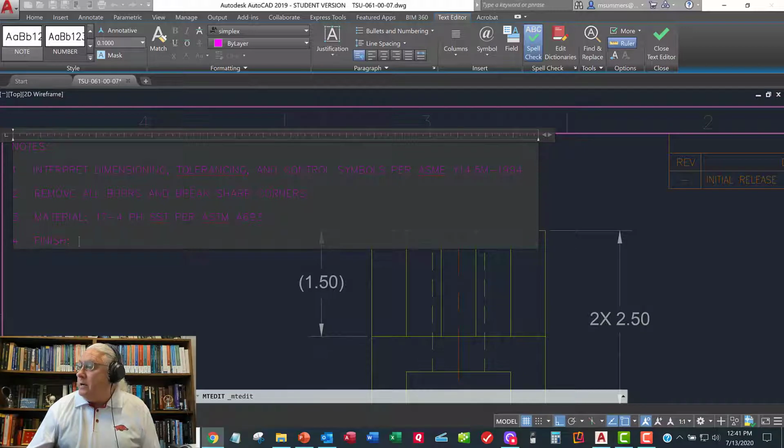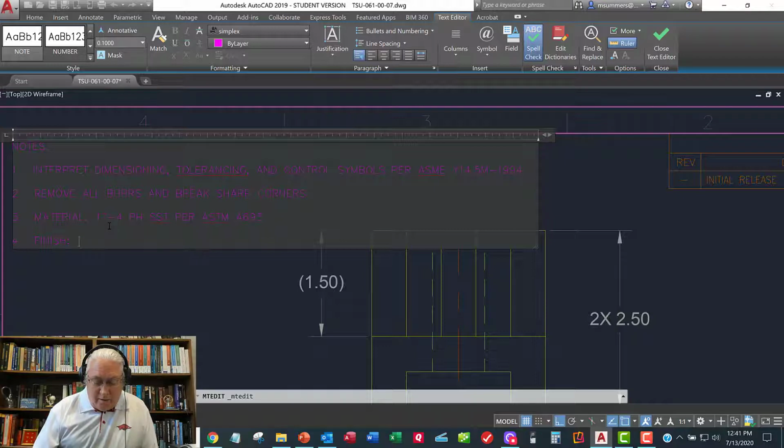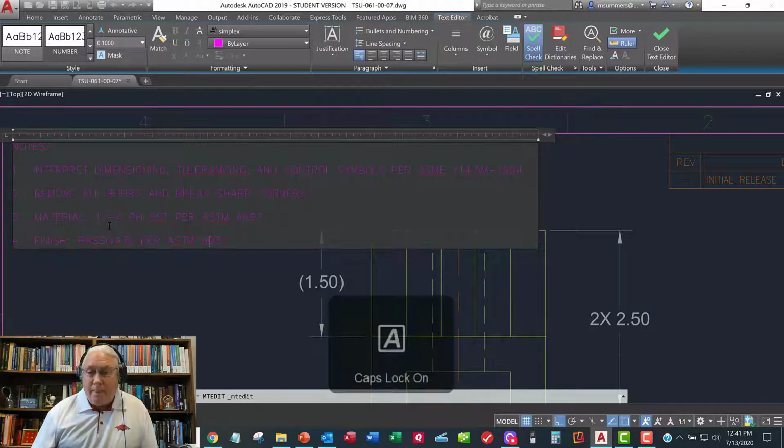So I'm going to come down here and type in passivate per ASTM A967. All right, and then I just click off of it.